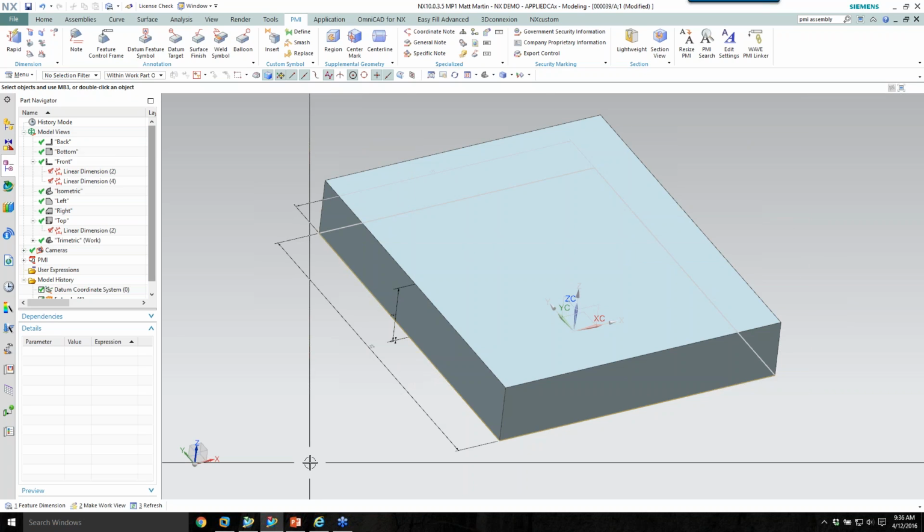Okay. And it is a different package. If you're running in Teamcenter, it makes it a little bit easier, but you don't have to be inside Teamcenter to make it work. It does use the JT representations and pulls all the PMI in, and that PMI is then used to analyze how the assembly is put together. But you still have to tell the system how it's put together. So in any complex assembly, you can assemble pseudo or sub-assemblies within it, and then put those sub-assemblies all together, and then you tell the system how that all goes together, and then it will do stack-up analysis to figure out what your build rate is if you have a failure rate.